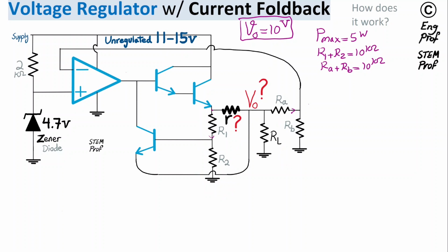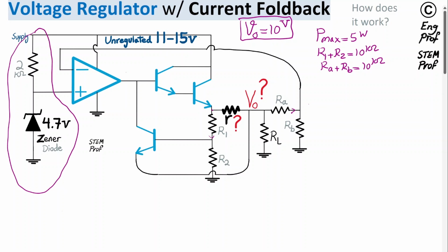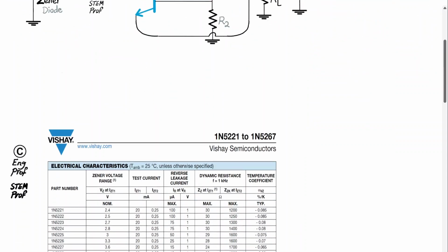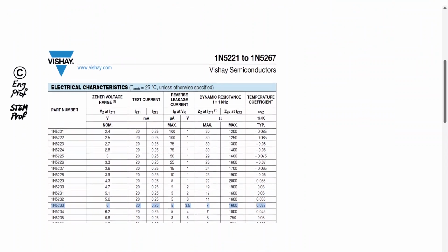The way the circuit is working is first establishing a reference voltage, accurate enough, like a band gap, that is done by this simple combination of a series of a 2K resistor with a Zener diode that has good temperature coefficients. For example, for 4.7 volt we can rely on a diode from Vishay Semiconductor.